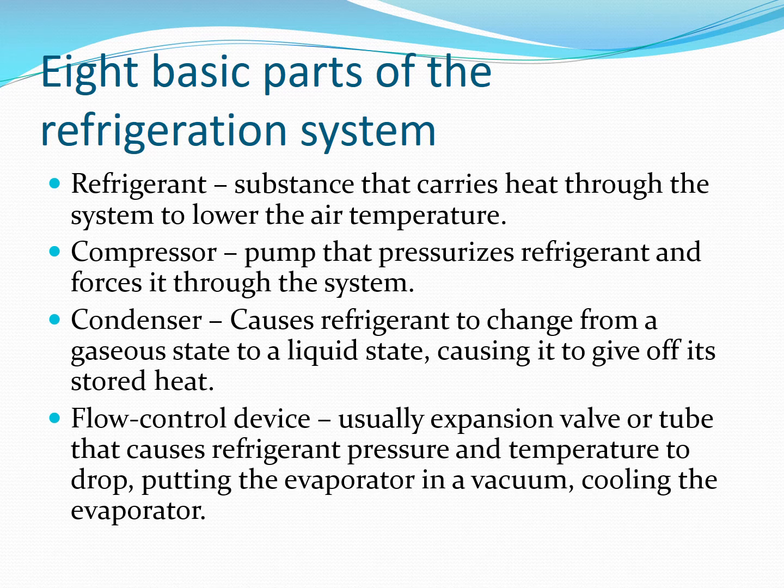You're going to have a flow control device. This is usually an expansion valve or a tube. But I think the important part to point out here is this is what is causing the pressure to drop. I gave the example earlier of the propane bottle. It's liquid inside the propane bottle, but as it leaves the valve at the top of the propane bottle and that propane hits atmospheric pressure, you have a sudden drop of pressure to cause it to be cold. So that is the flow control device in the automobile refrigeration system.